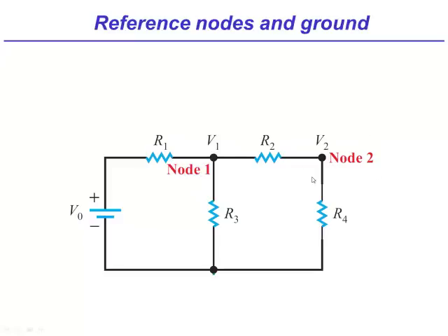But the important thing is, notice I've got a power supply here, and I've got some components, they're resistors, and they're connected by wires, and there's points where these wires sort of intersect and come together, and we'll call these nodes. So notice there's a node right here where these kind of come together. These are all at the same potential. And there's a node, and here's another one at the bottom. Okay, so this is a very simple circuit that we'll very quickly learn how to examine.